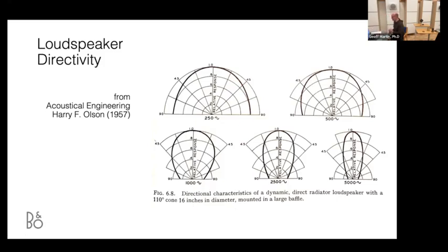They all have basically the same behavior, where at a very low frequency, where the wavelength of the signal is large, or is roughly on the same order as the size of the driver itself, or larger, then you basically have an omnidirectional radiator. So as we can see here, for a low frequency, we're less than 3 dB down at 90 degrees in this case.